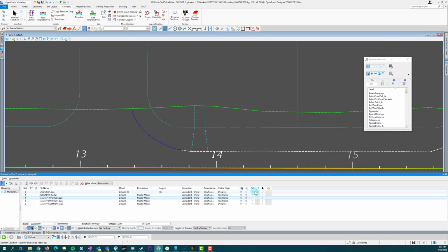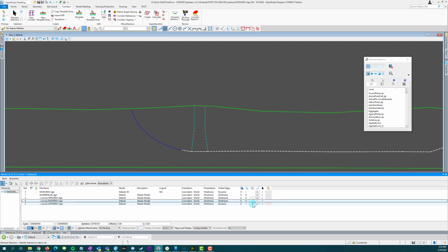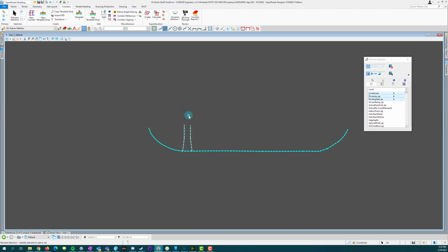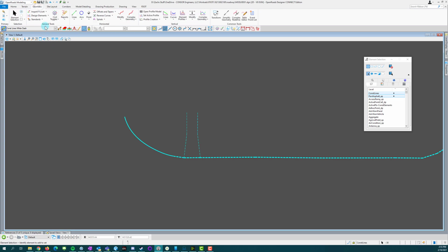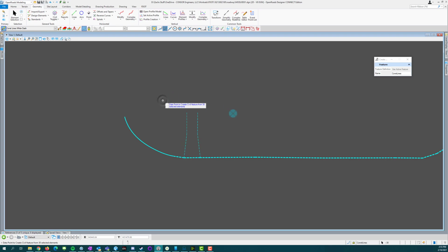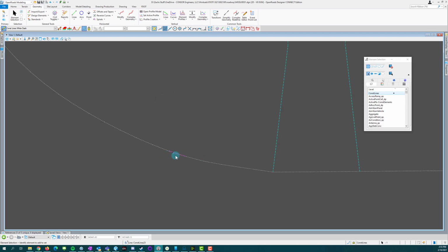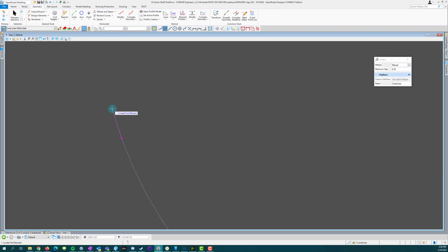So we've got that, and I'm going to drop these two driveway lines here. And what I want to do is rule some of this stuff. I'm just going to turn off some things here that make it easier for me to select this stuff. And I like using construction lines, white dash for my edge of pavement. And deselect these two. What I do first is I come in here and give it a rule first. I'm basically going to rule all of this, all the dumb lines, that's what I call them, into civil geometry. And then we can go ahead and complex those lines together.